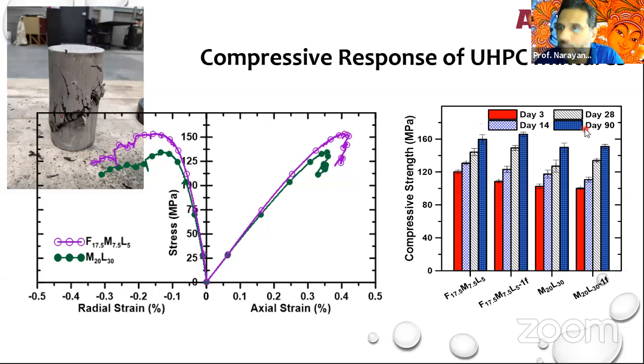I told you why we use limestone, especially when you have materials like fly ash, which has alumina in it. Limestone has the capacity to react with alumina from fly ash or slag to form what we call carboaluminates. That'll give you some additional strength. So rather than putting in quartz powder, which will just stay there, fine limestone powder will give you some additional strength enhancement. We need all the possible sources of strength. We don't want to miss out on anything because you are targeting an extremely high strength.